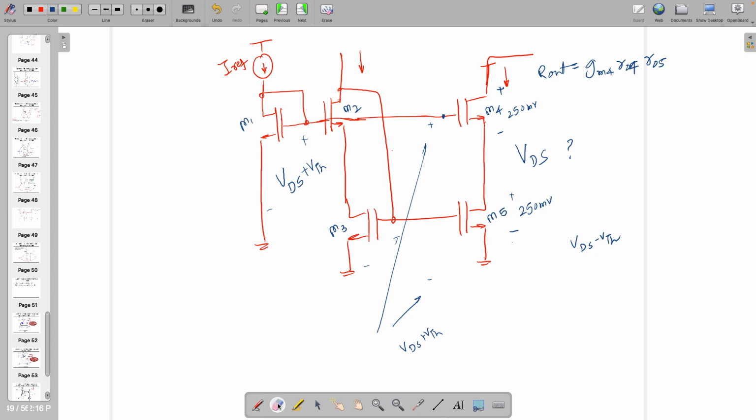So now find out. So minimum voltage here required is VDS. VDS is required. In addition to that, something is coming because of this biasing. It might be some other value also. Or if you want to do it this way, that you keep this to as VDS, then how much voltage is required here? 2 VDS plus VTH, right?